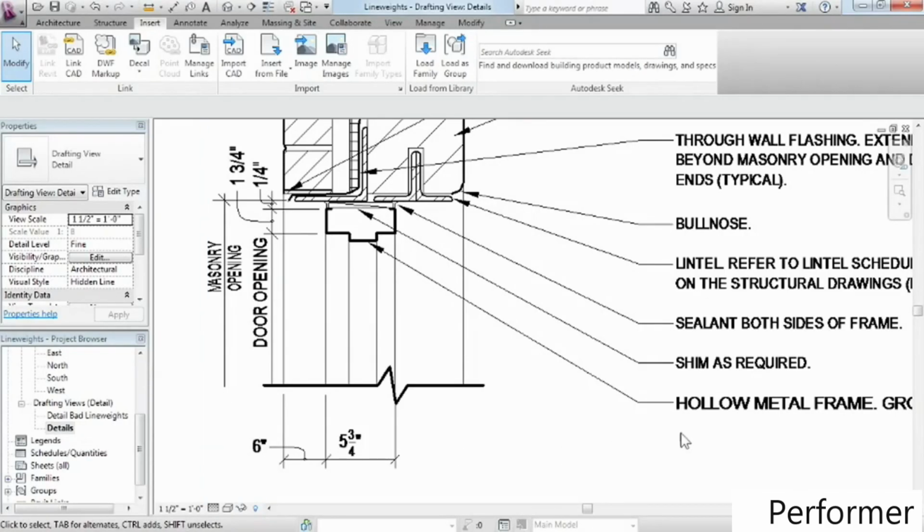Over here, you can see that this note looks a little different than this note. Back in CAD, this note uses the Simplex font, which is an SHX font. SHX is an AutoCAD-only technology. Revit doesn't understand what an SHX font is, so it's substituted a TrueType font in its place, and in this case, it used Arial. These up here, we're using Arial Narrow. If you want the fonts to display a certain font, you're better off actually going back to AutoCAD and changing all the fonts in AutoCAD first before you import them to Revit, because there's really no way to change them after the fact.